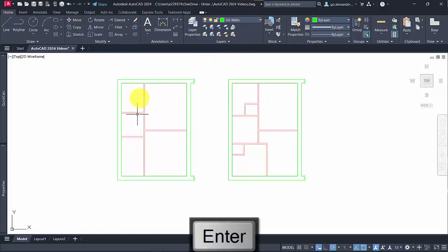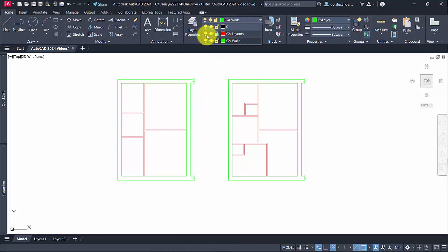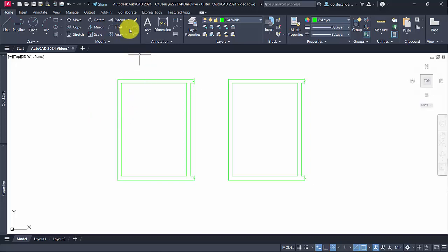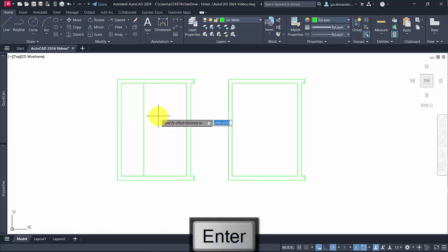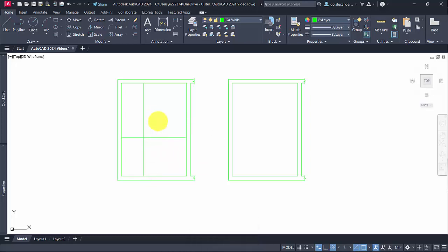Now at this stage you could trace over the layouts, but it is useful to hide that layer and just make sure that you're following the correct dimensions. It's a good opportunity to double check you've got all the dimensions correct if you're following the video. So 2000 millimeters for these 3 rooms, 3500 for the first one at the bottom, 2100.